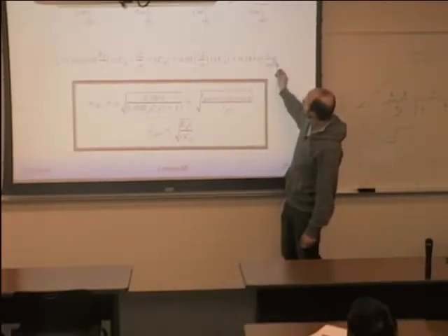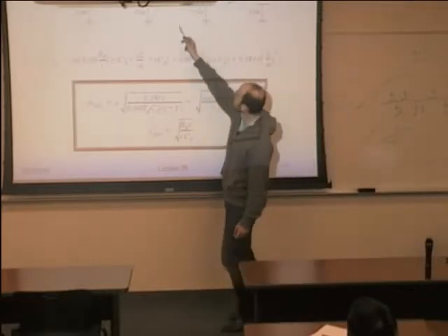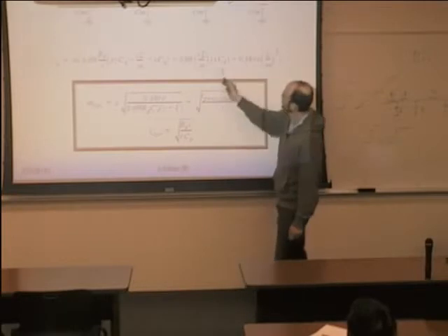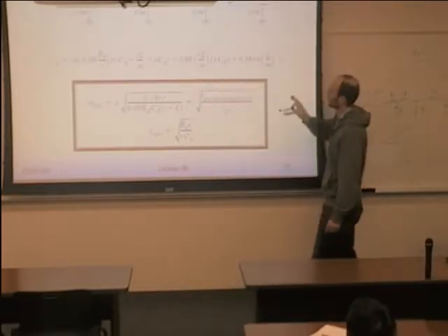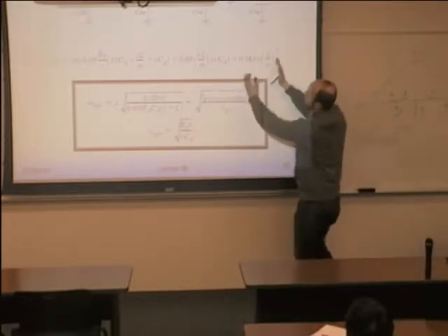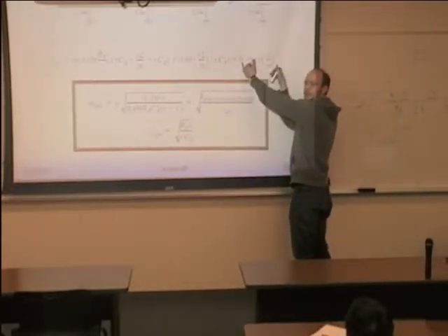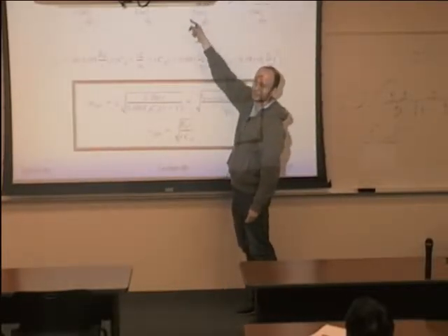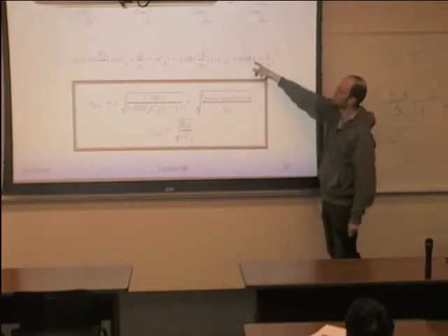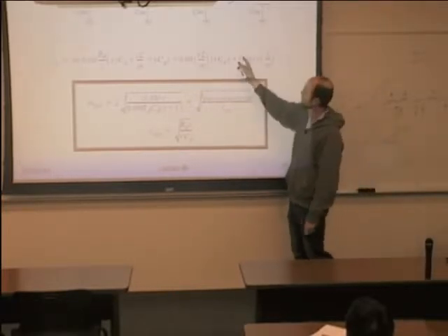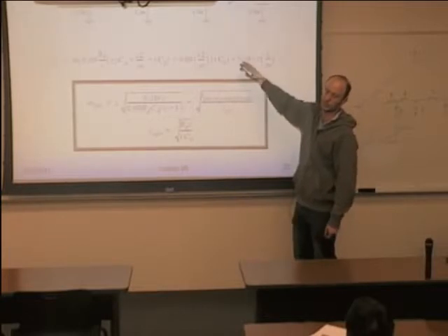So you can write then the delay of one section with this buffer present is equal to this. This might look a little daunting, but actually it's not that bad, because this part is the intrinsic delay of the wire when the length of the wire is 1/mth of the total length. You can see the R per unit length, C per unit length, and then the reduced length. And this constant, 0.7 divided by 2, takes into account the distributed effect.